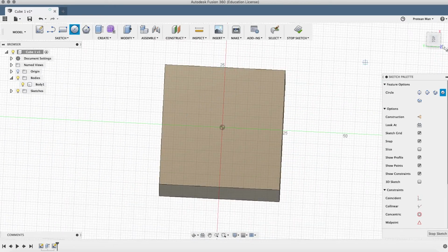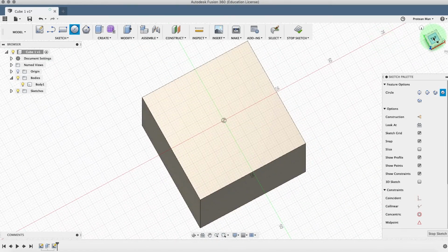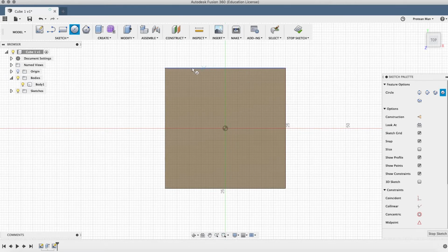So if I go again, let me just fix this, bring this around, make it back where it was, where the Y is vertical. Okay, so the X with the triangle is center. You can pull it all the way down. You can do the other one too, another side, an adjacent perpendicular line, and it should snap with two lines. And then all of a sudden, if I click on that center point and drag my mouse up, it will make a circle.